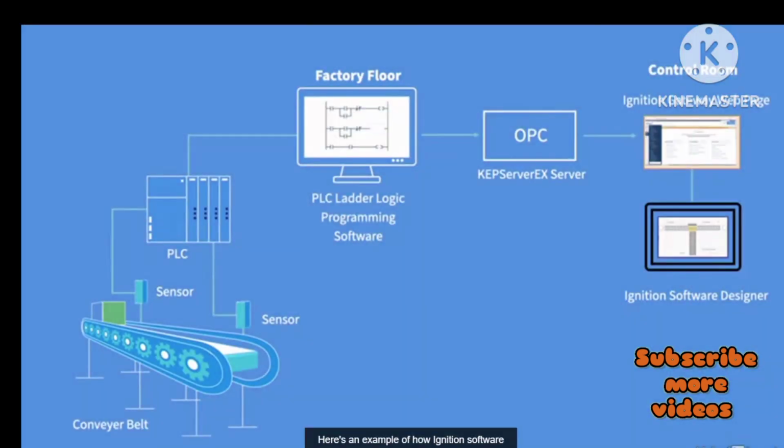Here's an example of how Ignition software fits in a SCADA project. Here I have data coming from sensors located on a conveyor belt, connected to a PLC, then using an OPC server. In the example you see, I'm using Kepware server to send data to Ignition software.